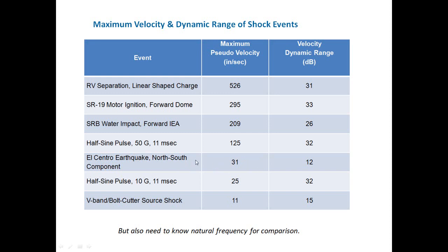But we cannot discard the earthquake altogether, because let's say we have a launch vehicle and it's on the pad at Vandenberg, California, which is conveniently located near the San Andreas Fault. There's a possibility that an earthquake could occur during the 2 weeks or so that launch vehicle is on the pad. But in that case, we would be concerned about how the low-frequency bending modes would be excited, more than what the avionics responses would be.